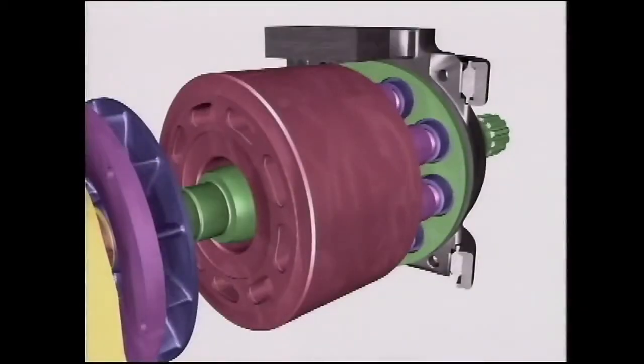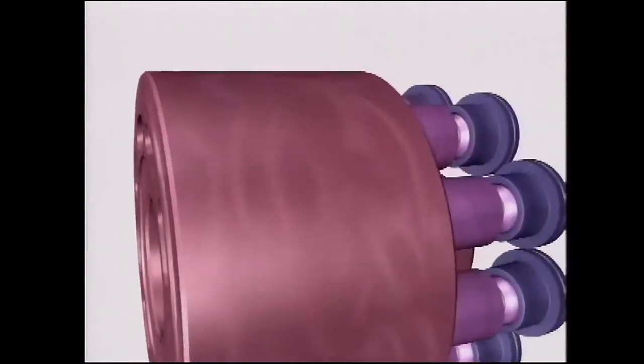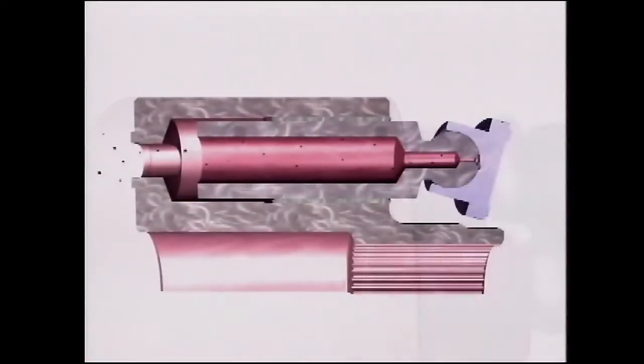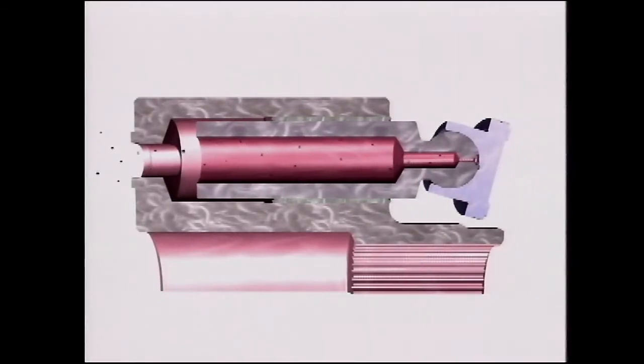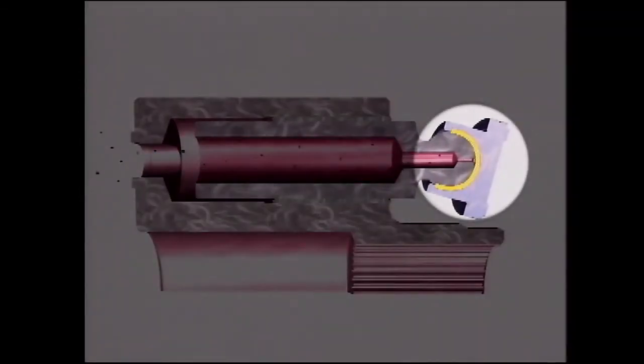As we look at other ways contamination can cause problems, we turn the animation of the pump 90 degrees onto its side. Particles can lodge between the piston and the brass slipper foot, shown here in purple, causing it to jam. The contaminants can also scrape walls between the barrel and piston.